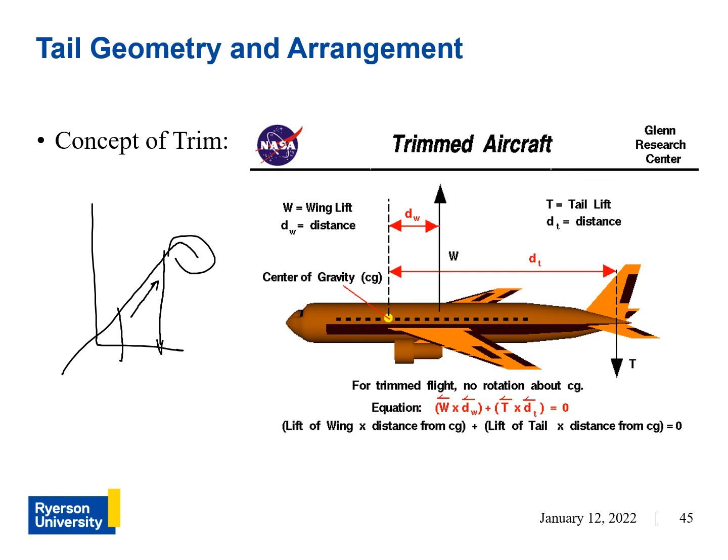So tails provide an aircraft trim, stability, and control. And again, trim refers to the generation of a lift force, acting through some tail moment arm, here, about the center of gravity, that balances the pitching moment produced by the wing body, which I explained earlier in this workshop.